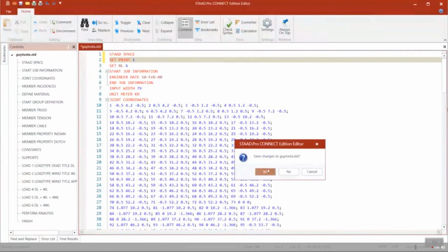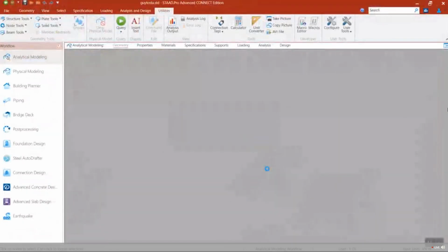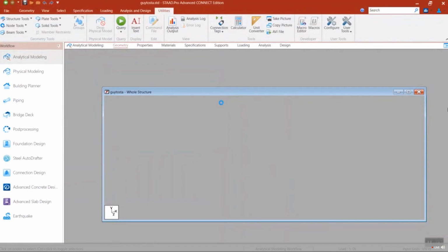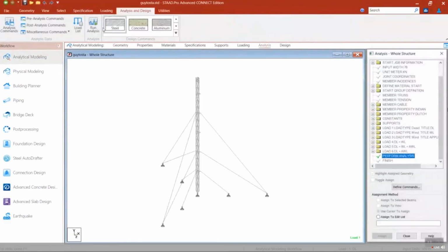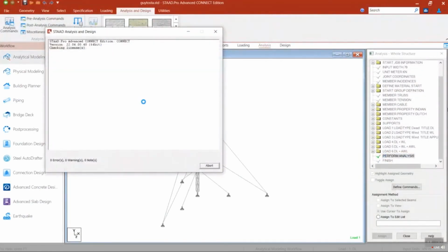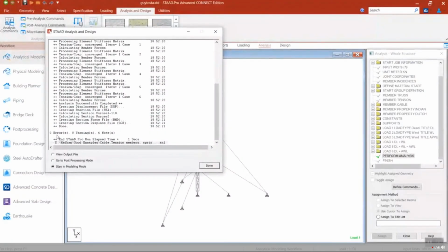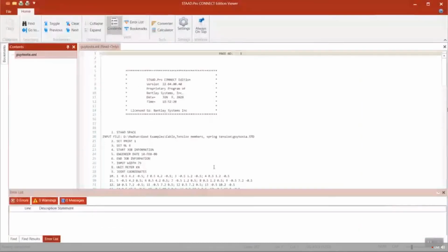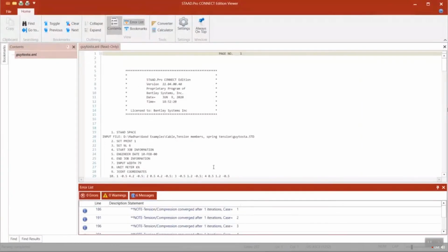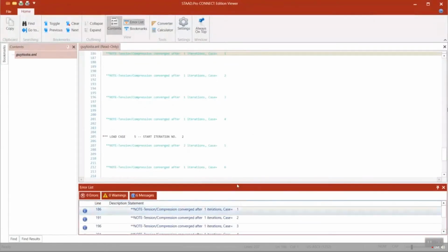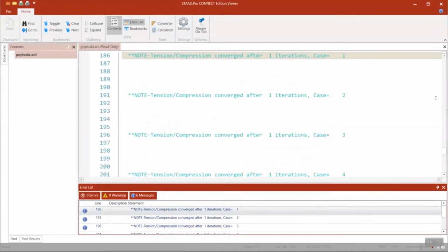So to suppress these warning messages, I use the SETPRINT 1 command. The SETPRINT 1 command will suppress this warning message. Only after you have gone through the warning message clearly and understood it clearly, then you use this SETPRINT 1 command to suppress the zero stiffness warning messages.